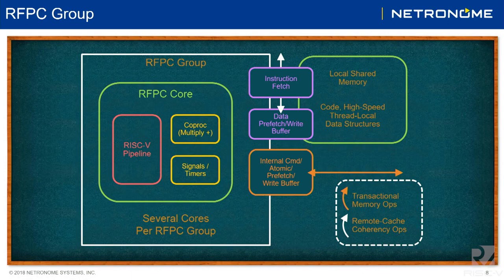One of the limitations of the 32-bit machine that we selected is that it only has a 32-bit address, which wasn't extensive enough for us. So the binding operation that goes from a local CPU address into a global CPU address expands that address space to greater than 48 bits of address, so we can have a reasonable address space for the processors to access.